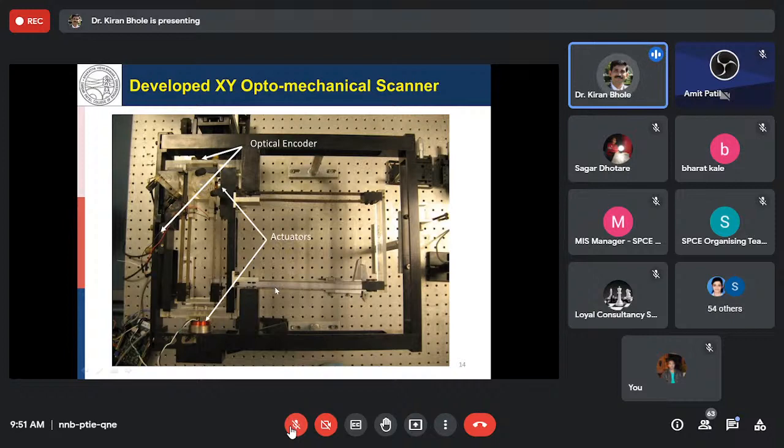The outer linkages you can see here are firmly fixed at this particular point, or the structure of this assembly. The inside linkages have this body on which the force is generated from the voice coil actuator. Again, we have used the voice coil actuator so that there won't be any deviation in the line of action of the force coming out from the actuator.